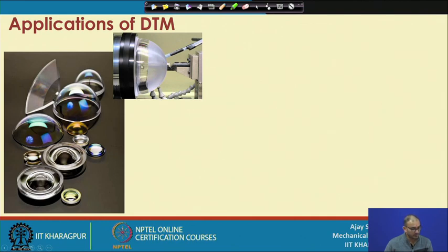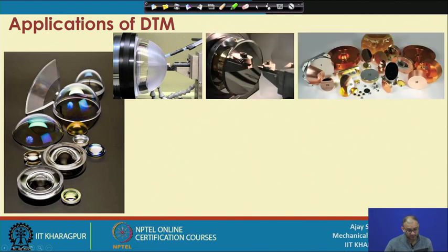This is one of the applications where polymer is being machined on a diamond turning operation, and most of the metals, non-ferrous mostly, because when you are using a diamond as a cutting tool, ferrous materials create problems because of the carbon migration from the workpiece to the tool, and because of that you will get a different type of wear on the diamond cutting tool very quickly compared to non-ferrous material. So, copper, aluminum, brass and different types of silicon are also some of the materials, and all these materials can be polished, and the surface finish is extremely high. You can quickly achieve less than 1 nanometer surface finish by setting optimum process parameters for the speed, feed and